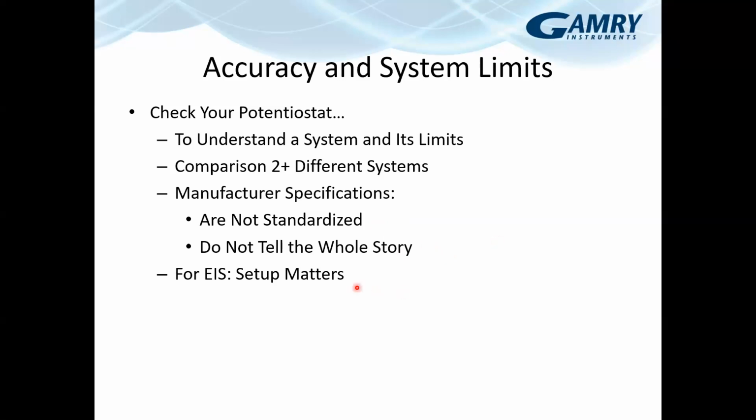The last thing here is that when you're doing EIS, your setup matters. I talk about the cable regularly because for both very high impedance systems like barrier coatings and for very low impedance systems like batteries and fuel cells, how your cell cable is connected can influence the results that you see.